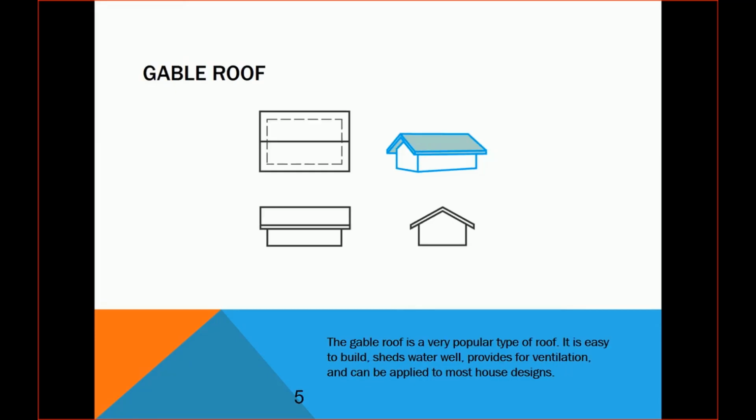A gable roof is kind of the opposite of that. The roof just continues on straight, doesn't have a slope at the end, and the wall material goes up into the peak of the roof. So gable roofs are very common. A lot of times we like to do gable roofs and put some kind of decorative window in that gable, or a window that's taller in a room or something like that. So that is a gable roof.